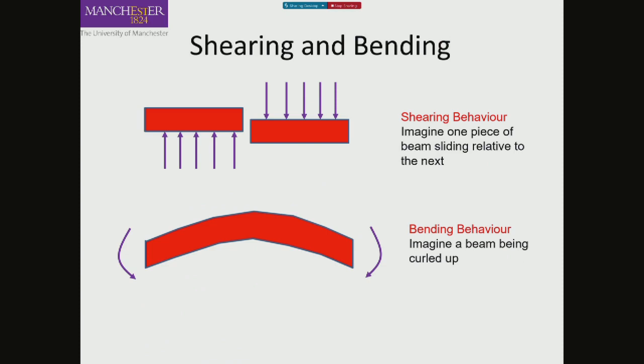So you can think of the beam as starting to bend to resist the load. So bending is an after effect of that deflection. You could have little or small deflection, depending on the material. If you have a very soft material, it will bend more than the other. But even if it is a very rigid structure, a beam that doesn't bend much, there would still be a bending moment. Okay? So the deflection or the bend profile is an after effect.